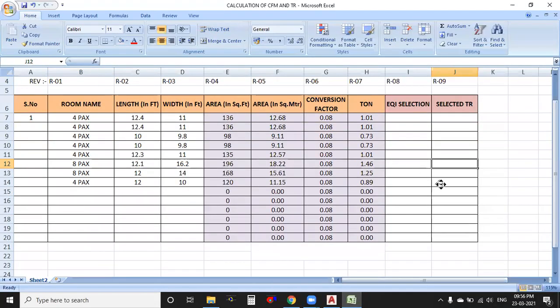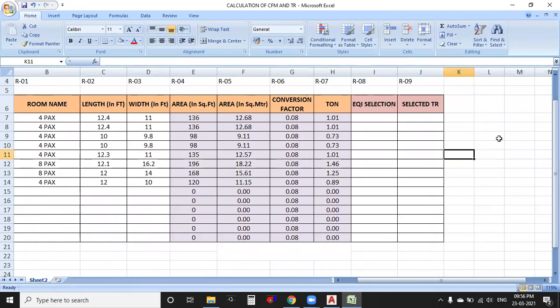Now I'm going here. In the market, air conditioning capacities are 1 ton, 1.5 ton, 2 ton, 2.5 ton, 3 ton. So in total the units we have are 1 ton, 1.5 ton, 2 ton, 2.5 ton. This is the availability of capacity of our equipment. Whenever we are working, try to select a maximum of 2.5 TR only. Don't select 3 TR. The reason behind this, tomorrow I'll discuss.